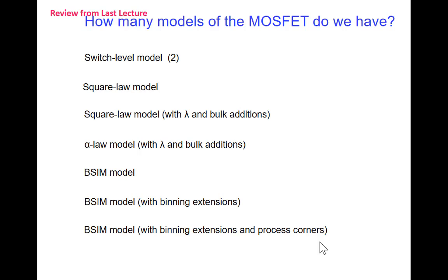Now, one thing that's happening is we're starting to take away the freedom that we're introducing in this course of allowing the designer complete control of the dimensions of the transistor, because what makes the modeling so difficult is that the characteristics depend upon the dimensions. So we're starting to see processes where they say you can have these transistors, these dimensions, and that's all you can have. And then they get empirical models, they measure model parameters for those transistors. If you want a device that's wider, you put 2 of them in parallel. If you want a device that's longer, you put 2 of them in series. Does that make sense? Instead of giving you complete control of the dimensions, they have a small number of devices you can put in parallel or in series. And that circumvents this issue of how do we get a model that accurately characterizes the IV characteristics when you change the dimensions of the device.